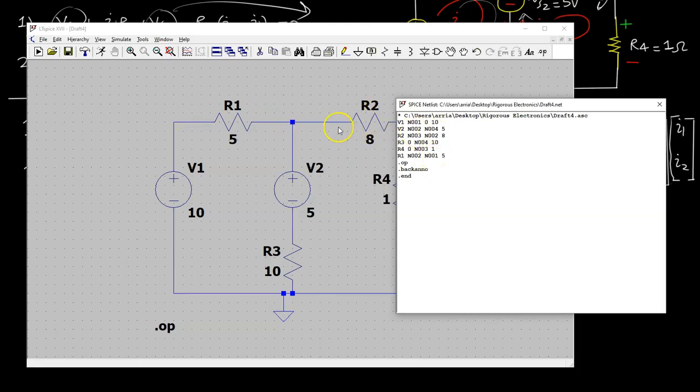And so the direction in which it's set is going to be reversed relative to what we've defined the current to flow, the passive sign convention basically. That's why you would get a negative number. It's assuming that plus is here, minus is here, current's going in this direction conventionally for this element. If you flip this resistor 180 degrees, you would see that the minus sign would go away, just because of the definition of this element.